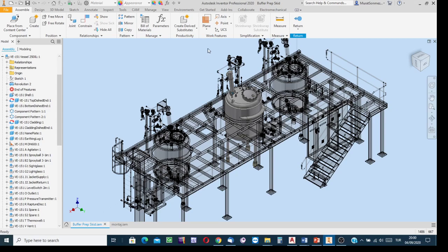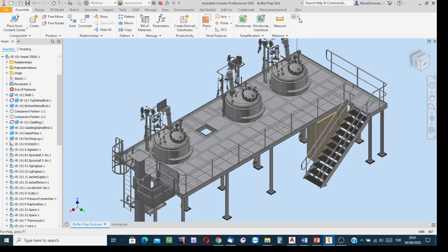But if your purpose is just to isolate it from the environment and just to have the sub-assembly in another volume, then, well, after starting editing process, click on return button. This is to turn back to the previous stage, well, the assembly environment, where we have in this example the main assembly.